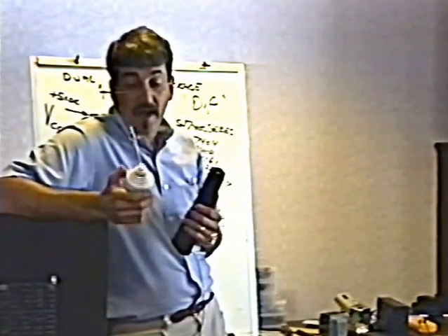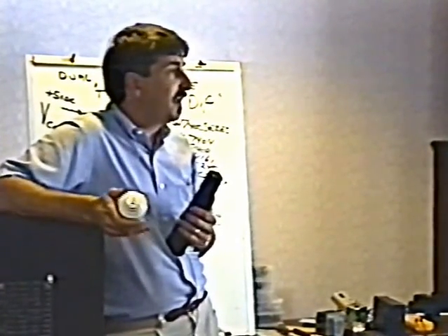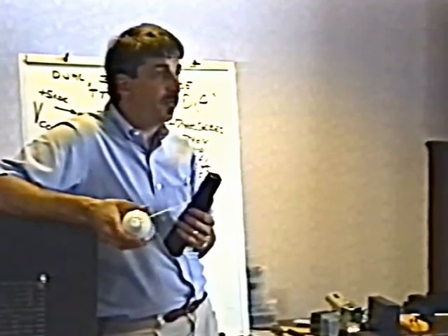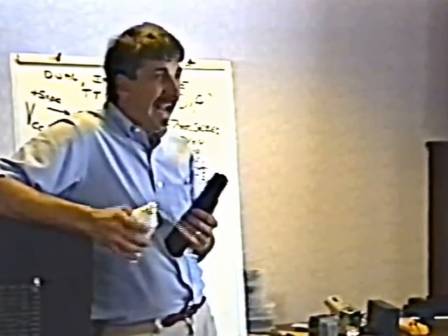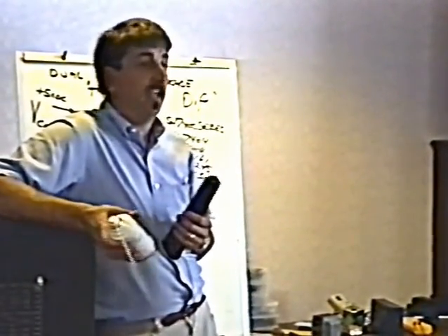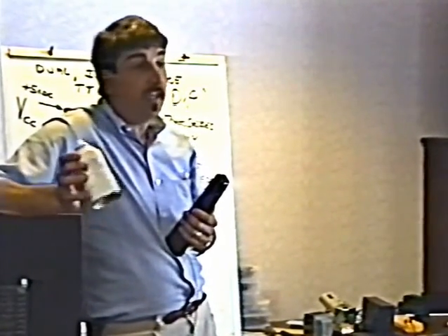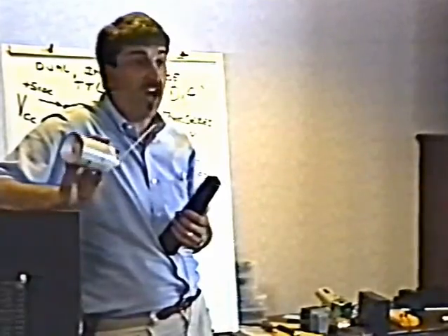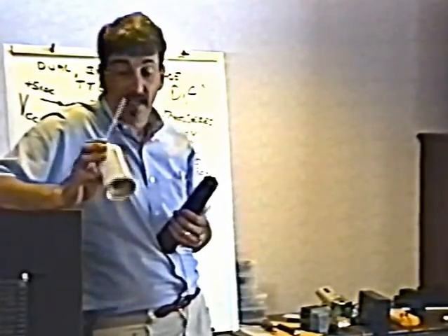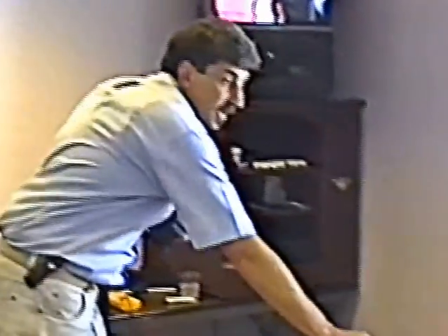And it works great, not only for things like this, but in a monitor if you have a thermally intermittent problem. Anything that works when it's cold but fails when it gets hot can be found by freezing it. So that's a really cool method that works great, and I've fixed tons and tons of boards this way. Like I said, I've never failed to fix a thermally intermittent problem with freeze mist. Always been able to find it.